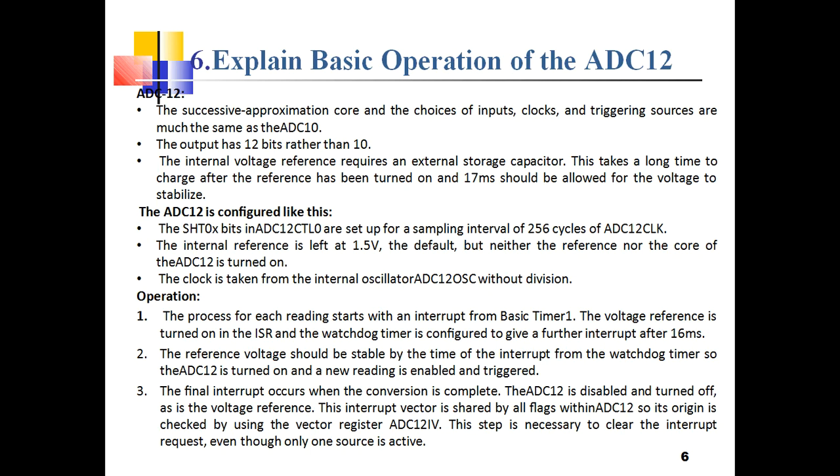The internal reference voltage is left at 1.5 volt by default, but neither the reference nor the core of ADC12 is turned on. The clock is taken from the internal clock oscillator, ADC12OSC, without division. Directly we are going to take the clock from the internal oscillator.